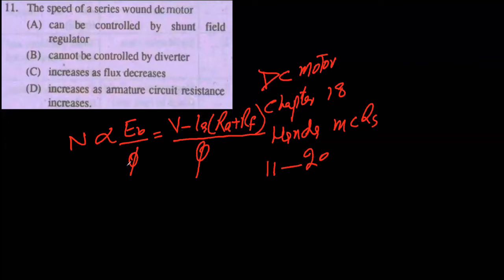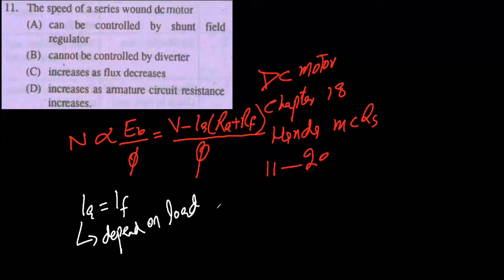So actually in a series motor, my IA is equal to IF. And your IA depends on load. On light load, your IA will be less.